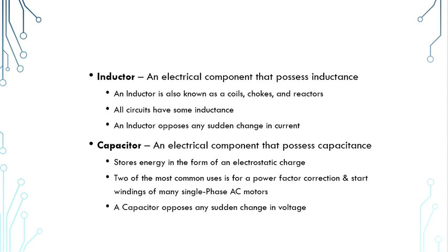Now, if we have start windings on a motor, remember we have to have some kind of a switch to remove those start windings. Otherwise, they would burn up real quick. Now, a capacitor will oppose any sudden change in voltage.